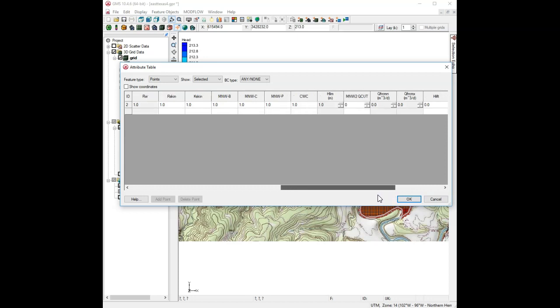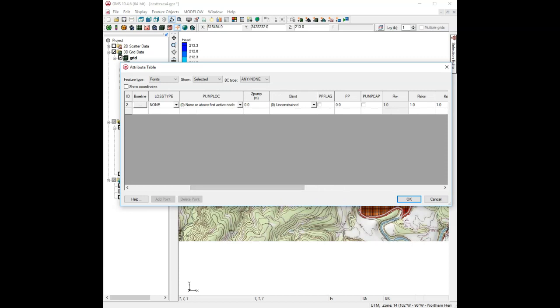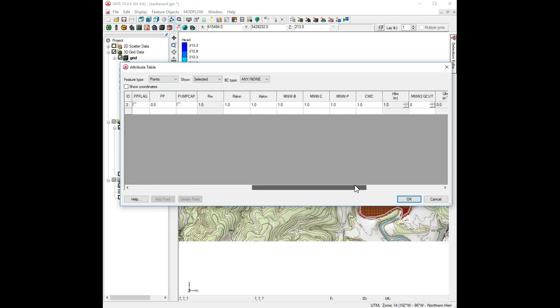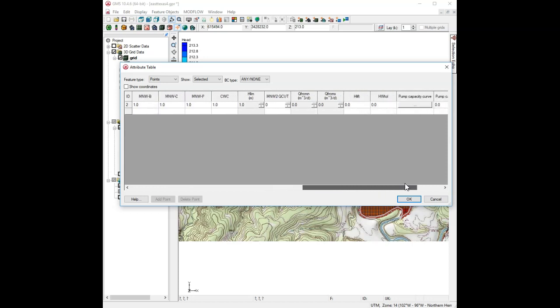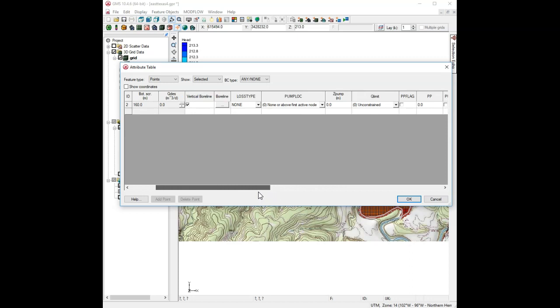This is used to do a really accurate representation of the flow into wells and how it's partitioned, and instead of specifying the pumping rate, you can specify the flow rate if you want, so there are a lot of different options. We are going to specify our pumping rate, so we're going to go over until we find a property called QDES. Where is it? Let's see.